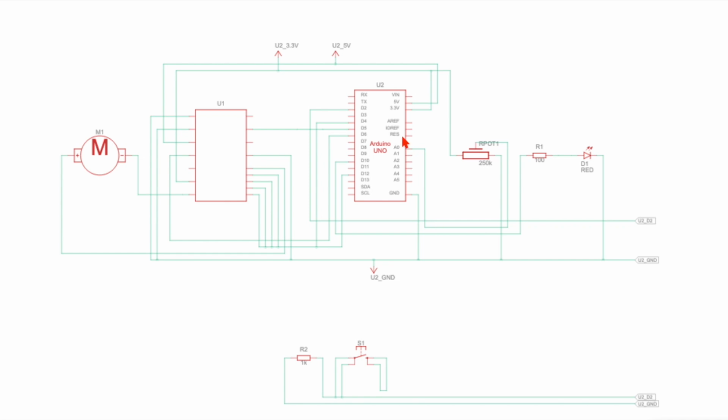The next on the parts of the circuit coming from the Arduino, we have the LED, which comes from ground from the board into the LED through the resistor and into the digital output of the Arduino. I just followed that in reverse because it's easier to start in reverse from the ground for these.